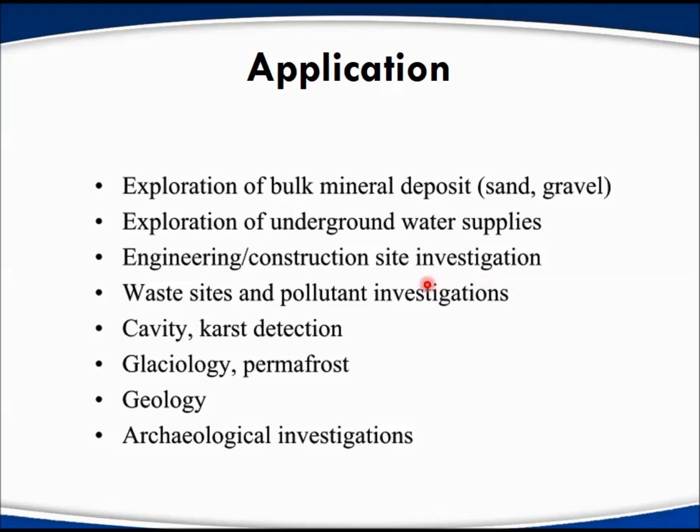The electrical resistivity survey is also rather useful in identifying waste sites or landfills, to study ground pollution, like how the liquid from the landfill penetrates or leaks into the ground and contaminates the groundwater. Cavity and karst detection is one of the famous aims of resistivity surveys, because of the ability to detect the presence of geohazard subsurface problems for development purposes, especially in areas with carbonate bedrock. In KL we have KL limestone, and in Ipoh we have Kinta limestone.